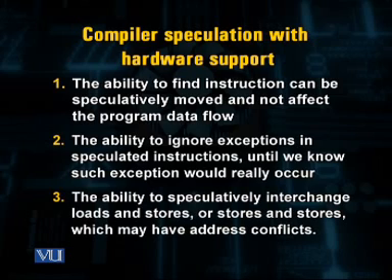And the third one is that it should have the ability to speculatively interchange the load and store instructions, or the store and store instructions which may have an address conflict, because these are the types of instructions which can create problems. Note that the ability to speculate is compiler based, whereas the other two abilities can be achieved by hardware support.